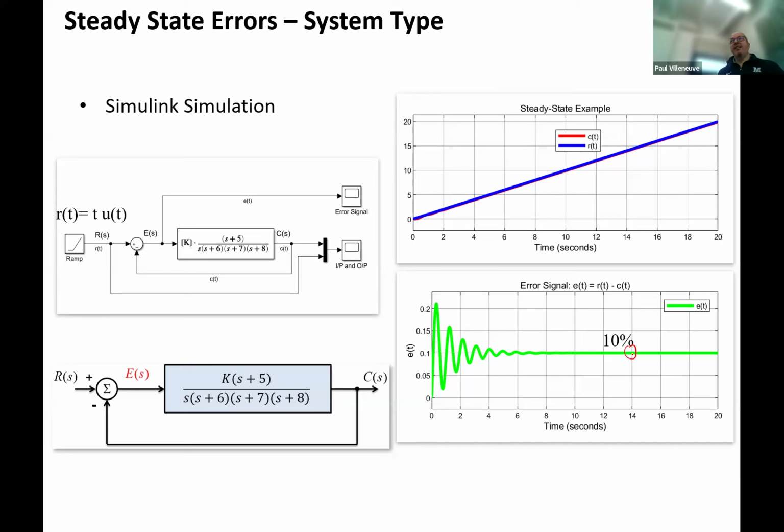And remember, this is not a second order system response where we want the maximum percent overshoot to be less than 10%. We said we wanted this value to be 10% or less. So that would be a separate design criteria to say that error doesn't have to, usually you don't worry so much about the error. Usually you worry about the output signal. Is it going to ring? And if you look over here, it's hard to tell, but there is some ringing. If you look really closely there, you can see the red line. So there is some ringing that happens at that value. It's just that you can't see it because we're zoomed in enough to see that it shoots up from there. So it does have a little bit of oscillation at low time, but in increased time, it goes away.